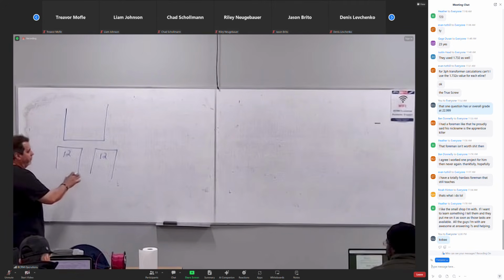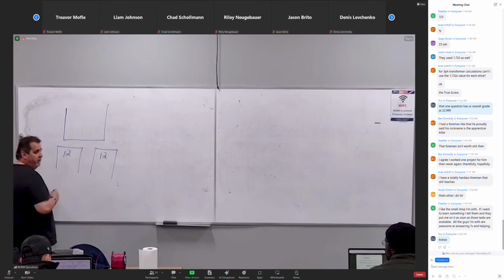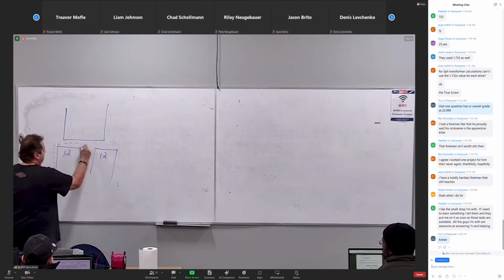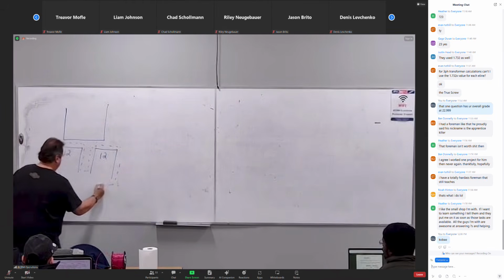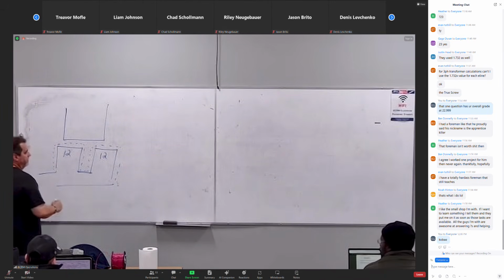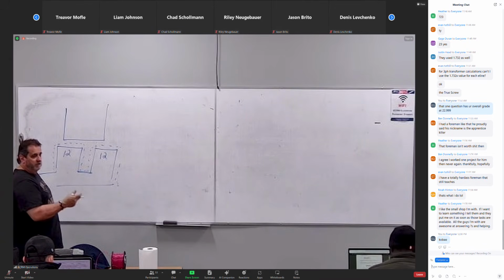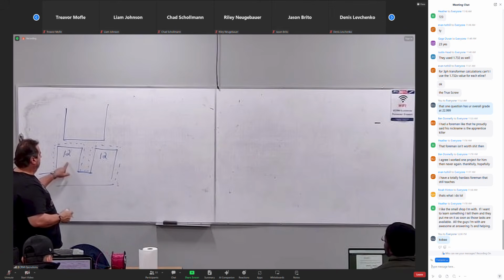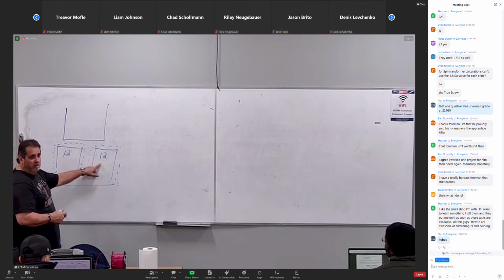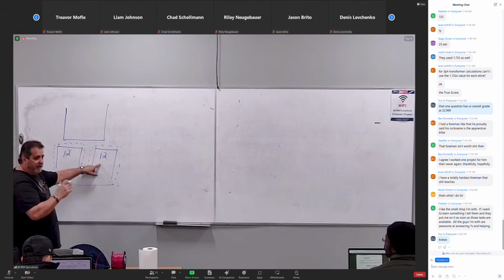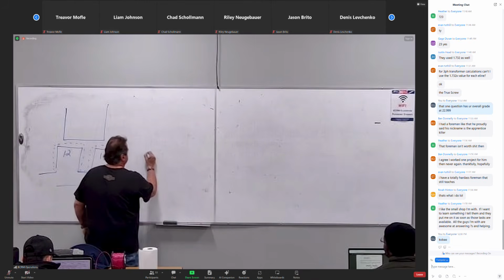So if I want 24 volts, I want to make this additive, which means I need to connect them in what? Series. One path in, follow it. I have to come here, go like this, and out. I put them in series. That's 24 volts. Parallel, E1 equals E2 equals E3. Well, if E1 equals E2, whether it be primary or secondary, it doesn't matter. I'm gonna hook them up in parallel.